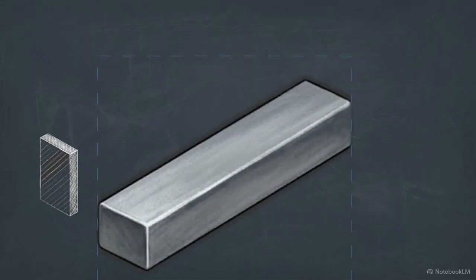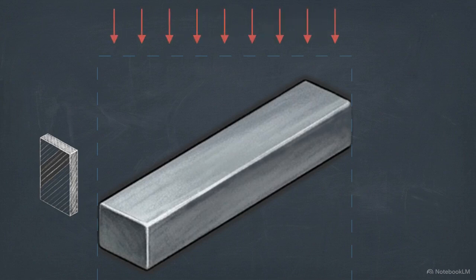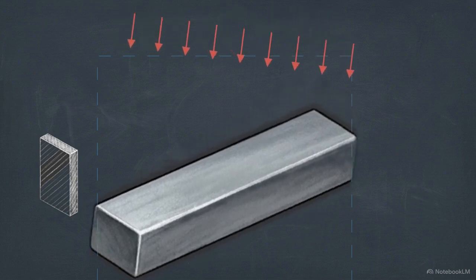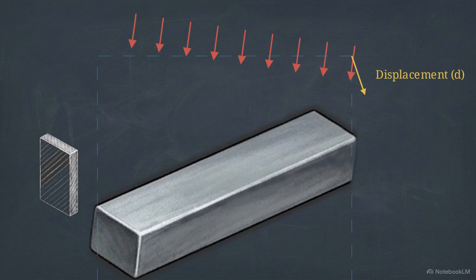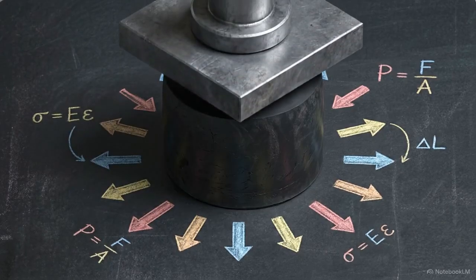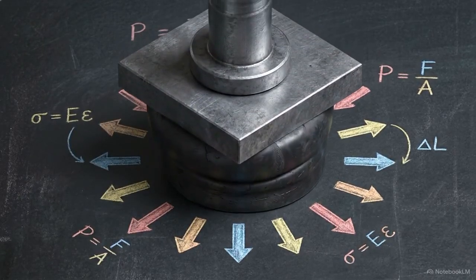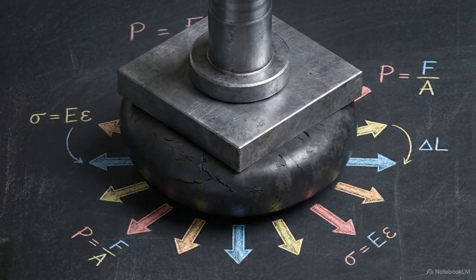The third energy component required is external work, denoted by W. The fundamental definition of work is a force multiplied by a displacement. Applied structural forces can be concentrated at single points or broadly distributed across a surface. When the specific point where a force is applied moves as the structure deforms, that force performs work. These massive external loads perform work by pumping energy into the system as the structure displaces under pressure.